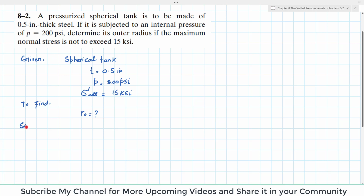As we know that for spherical tank we have allowable stress is equal to P into R divided by 2T, where P is the internal pressure, R is inner radius, T is thickness, and sigma allowable is the maximum stress. So from here you will get R, which is the internal radius, and that R is equal to 2 into T into sigma allowable divided by P. This will give you R.